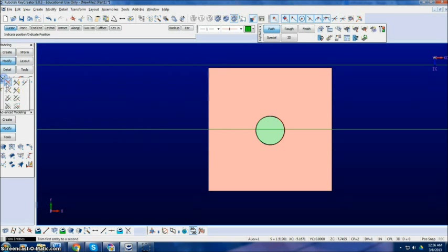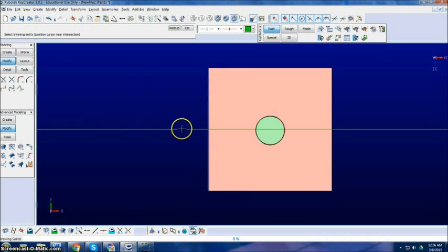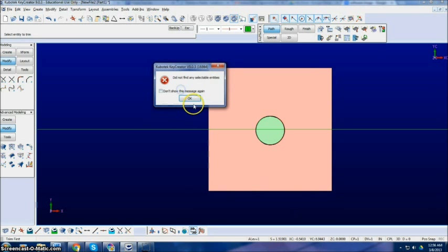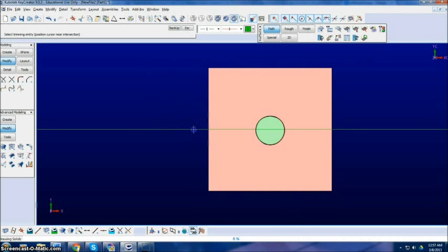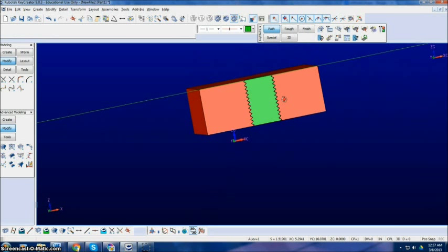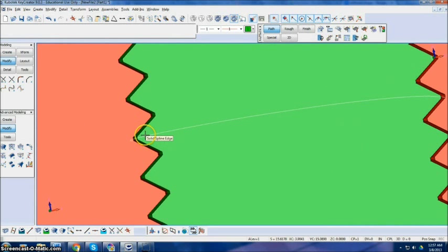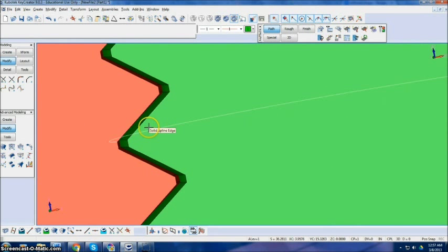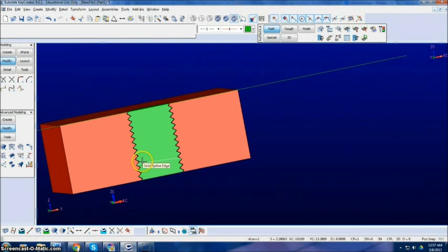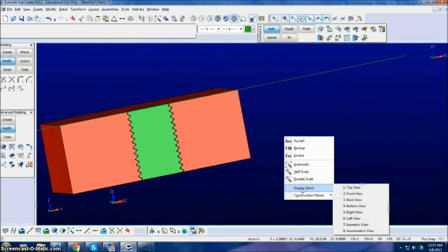Alright, so we'll modify trim first, solid to the line. Help if I put my construction plane in the top. And now the bolt to the line. Delete my diagonal line. Alright, if we get in there and look, we have a fair amount of clearance. So that should thread in no problem. The resolution on the 3D printer that we have is fairly good, so I'm sure that will work.